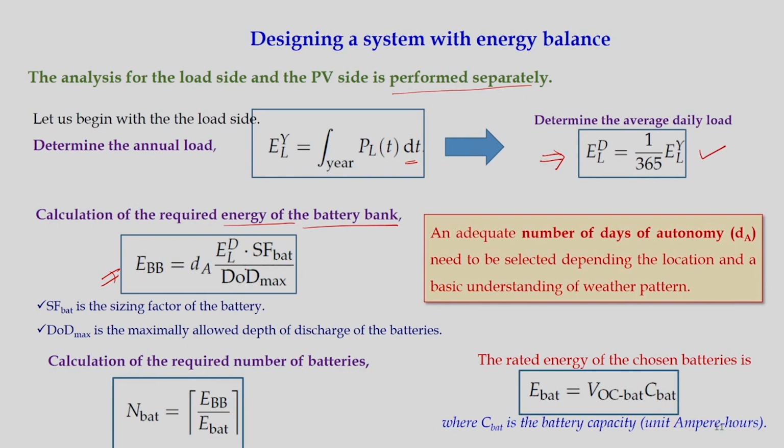And this SF is the charging factor of the battery. Normally its value is 1.1 or 1.2. And this DOD is the depth of discharge. There is a maximum depth of discharge we need to consider, and this can be evaluated using what we have already discussed.